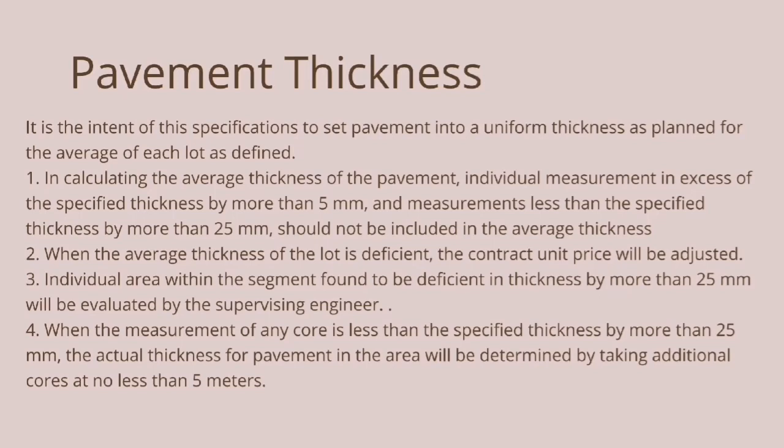So first, in calculating the average thickness of the pavement, individual measurement in excess of the specified thickness by more than 5 mm and the measurement less than the specified thickness by more than 25 mm should not be included in the average thickness.